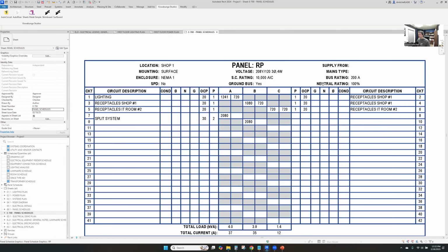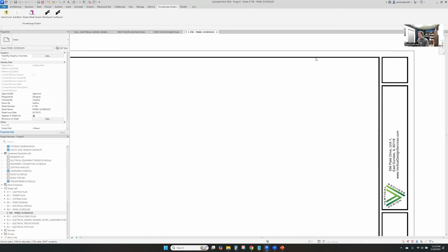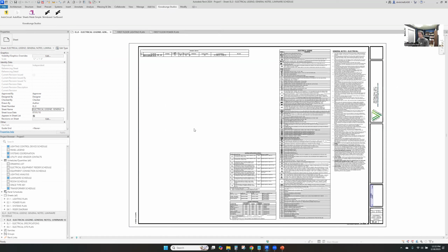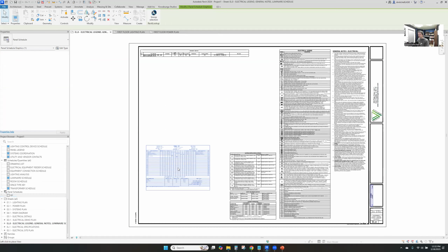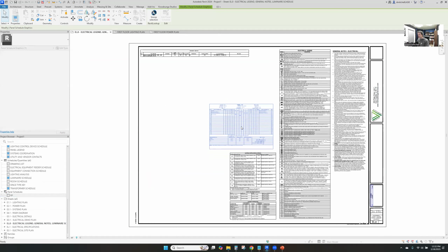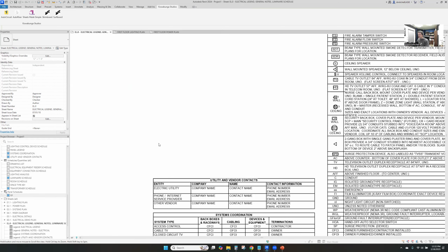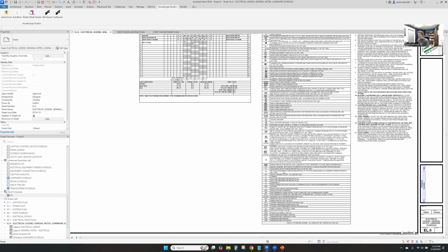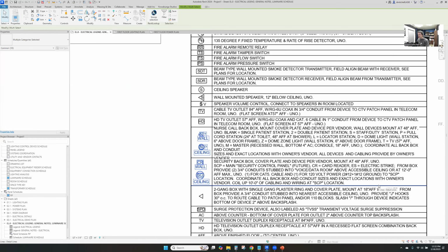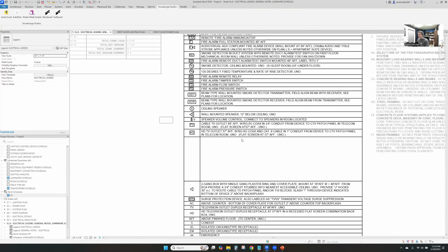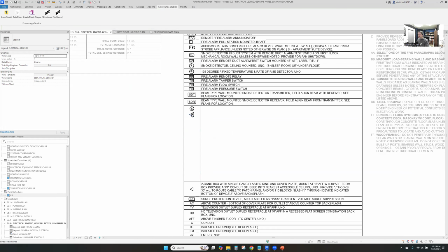Here's our initial panel schedule. And actually, because we're only going to have one for this, we'll delete these panel schedule sheets. And then what I like to do for a single panel schedule sheet is basically just add it in here. Because we don't have a ton of complicated controls, vendors, or any of this other coordination, that goes away. We're not doing any nurse call or card readers, so these go away. We're not doing any TVs, speakers, nothing like this. These go away.